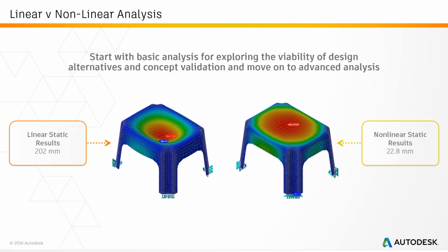So you may start with linear static analysis, but then we do recommend that for many applications you run non-linear for a much more accurate and realistic result.